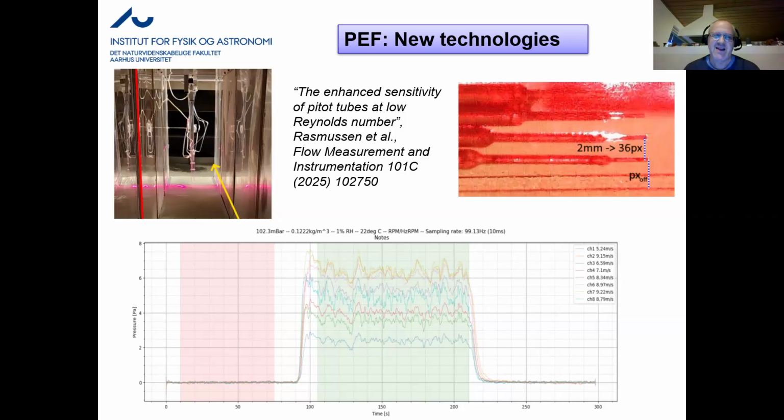One is that they don't really block due to sand grains. They're so small. You can see there's a microscope picture on the right. The outer diameter of the pitot tube is 0.4 millimeters. We have essentially only seen one time that one has blocked.